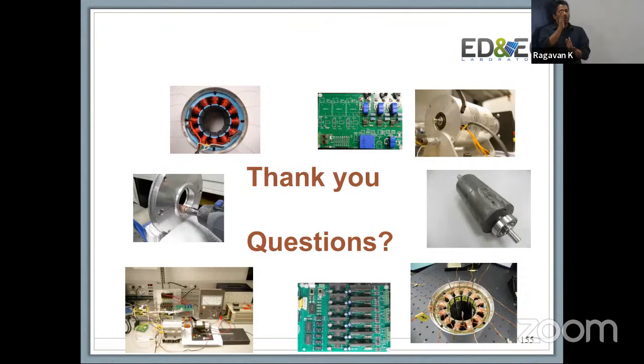Basically, based on your current switching state and the known value of current from the healthy machine, they would extrapolate the information of what the current should look like or is going to look like for this condition. So they would basically create a limp-back-home strategy for the motor. That was done by a gentleman named Haining Wang and Professor Fahimi back in the day. So there are methods that have looked specifically at failures that are somewhat catastrophic in nature. But in our case, we started off with the understanding that my position sensor is available and functioning at the beginning.